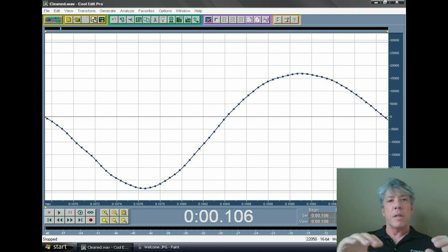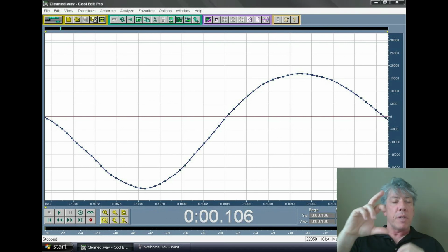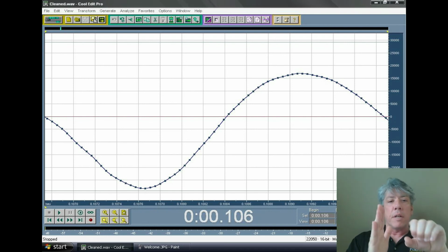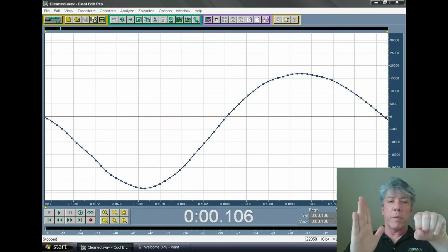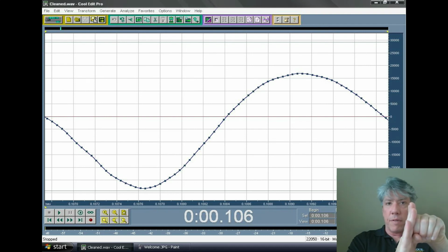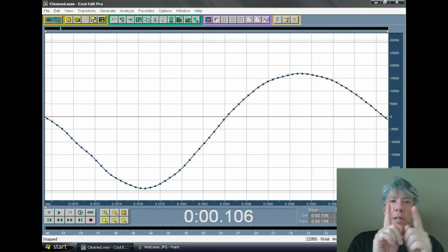The reason for that is because the waveform itself is decreasing. Now the resolution's not changed, right? The entire range from speaker all the way as far as it can go this way to all the way it can go this way. One position 0, the other one 65535. Okay, so if the speaker is being made to move back and forth at a lower amplitude, which is what makes it sound like a lower volume, then the number of positions it has available over that constrained, smaller range as it fades out is smaller, and so the precision of measurement goes down. And as you boost the volume, you'll hear it become quite scratchy towards the end. So it's just an experiment you can perform if you're interested in it.